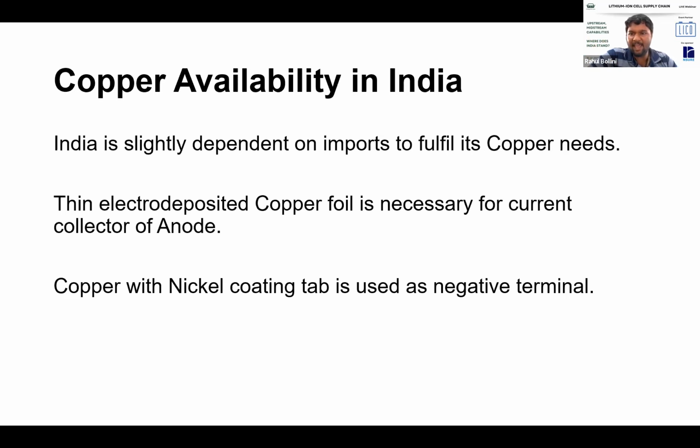That's where sometimes I tend to do a CT scan of the cell just to look at the thickness of it to understand. Because for the sake of telling, people can tell that it can work at any kind of C rating, no problem. But the efficiency of the tab to pass on that kind of current matters, because every square mm of copper used has a current carrying capacity. So you cannot expect copper to be used in minimum quantities and expect unlimited current. Say, for example, the best of the copper cannot give you more than 6 amps per square mm. So if someone claims, I will give you 60 amps of continuous discharge and the copper is not 10 square mm, then it's going to be a challenge. There's going to be a lot of heat built up, and we can even expect fires if it's NMC and NCA batteries.